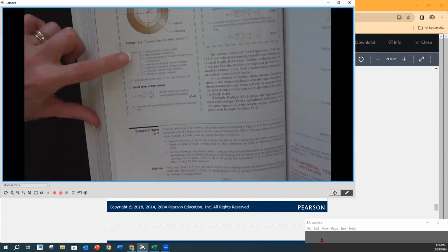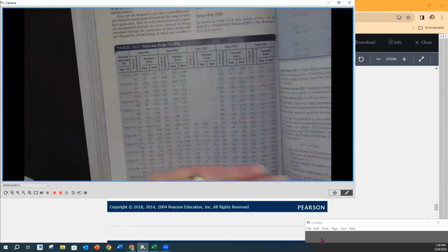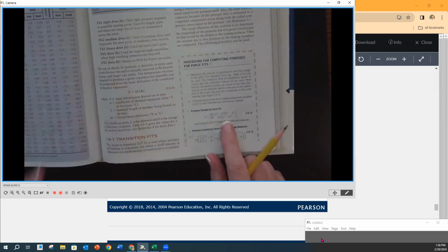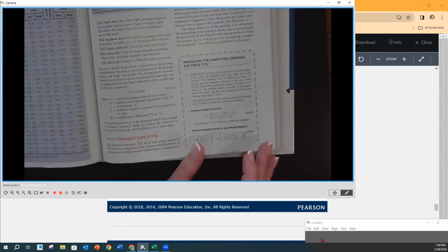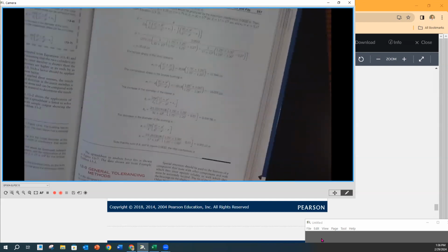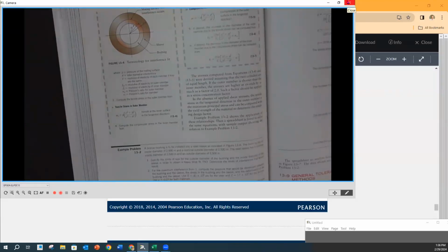So you'll notice that they give you all the items for what each one means. Now, the other one that's on here, maybe I missed it when I looked at it. It was on the second one. They didn't have it in the first one, but on the second one, you'll notice that they have these cursive VO and cursive VI. That's Poisson's ratio. And Poisson's ratio, as you guys know, is going to be how that material reacts when it's being pulled on. So Poisson's ratio identifies, as we go along, the length of something that's axial strain. But then that axial strain has to come from somewhere.